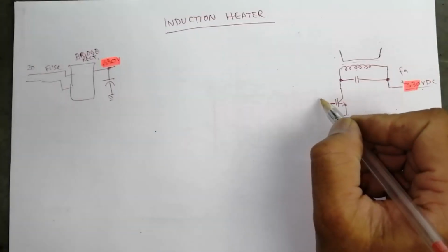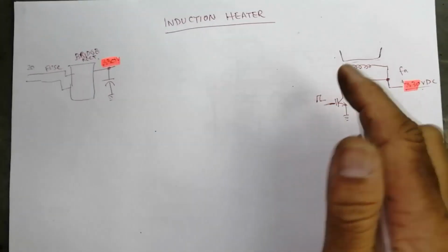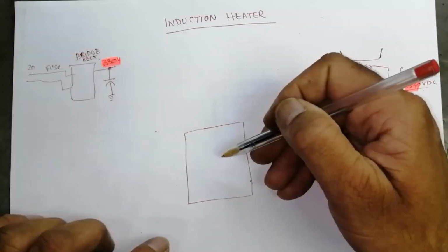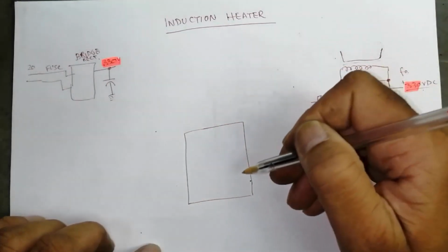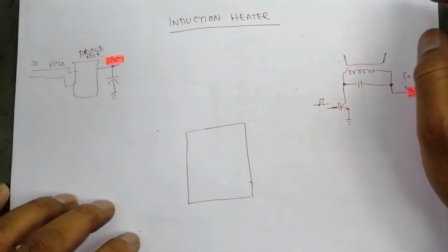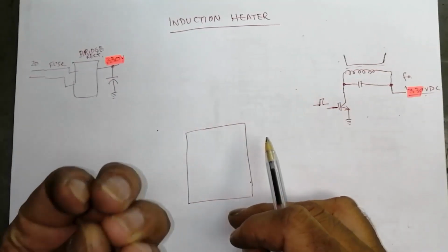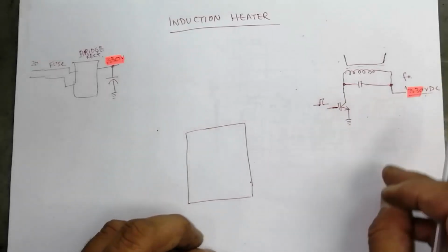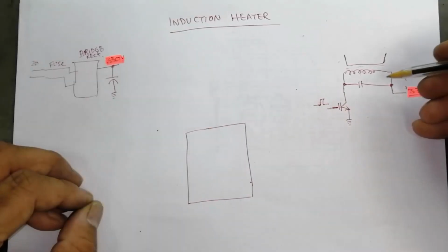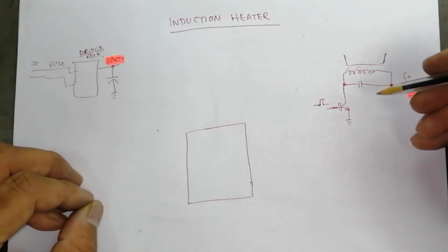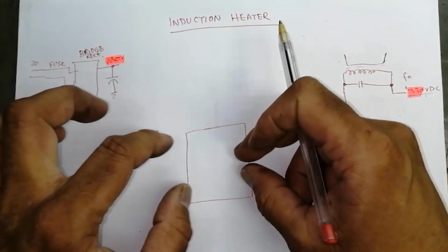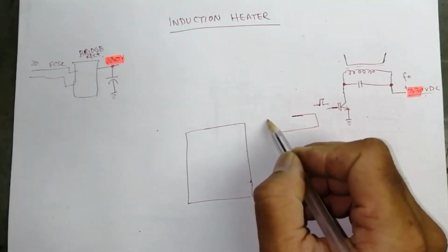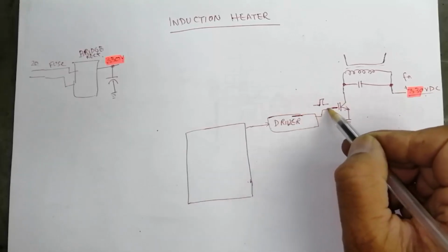We need a pulse, we need a drive signal, PWM drive. Most of the cookers use microcontrollers, processors, anything which can take software to monitor safeties, to monitor temperature. We will discuss everything step by step. They have to monitor different things, and then they have to apply a signal here. Then we have a driver circuit, and this driver is applied here.